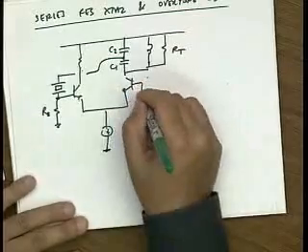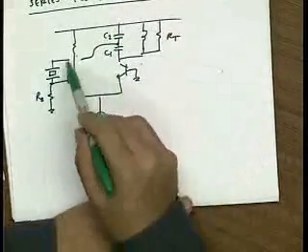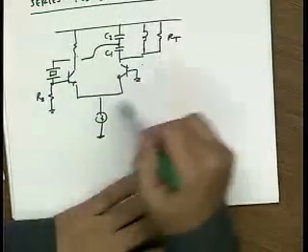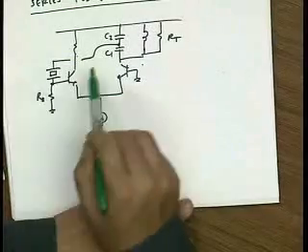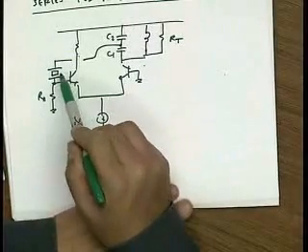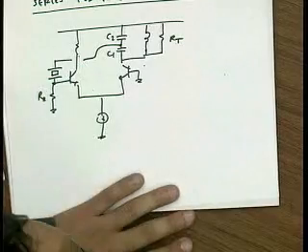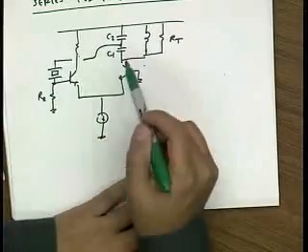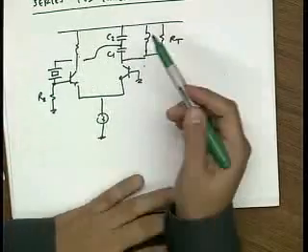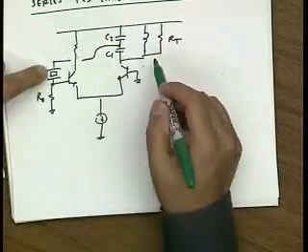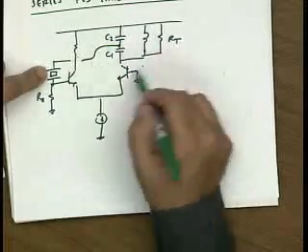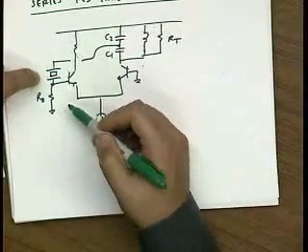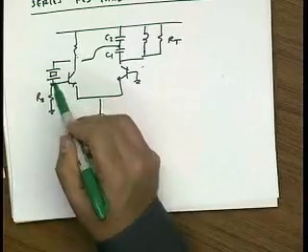That means that at series resonance, I just see Rx here and I see a voltage divider in the loop, so that determines the loop gain at resonance. If I move away from resonance, this thing either looks like a capacitor or an inductor, and it produces a voltage divider which actually kills the loop gain. So if I didn't have this crystal, if I just shorted this, the frequency response would be determined by this tank. But because I've put this in the feedback loop, the frequency response of the feedback is now a function of the crystal.